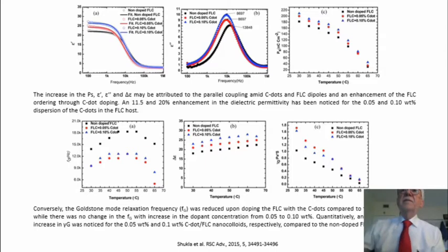And for the term of dielectric strength, this dielectric strength increases, as you can see, for 0.1%, much higher compared to the non-doped ferroelectric liquid crystal. And this increase will go up to 65 degrees centigrade. And finally, the variation of the gamma as a function of the temperature. Again, there is an increase of 79% when we add the 0.1% carbon dust in the matrix.